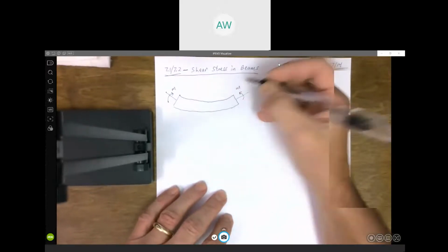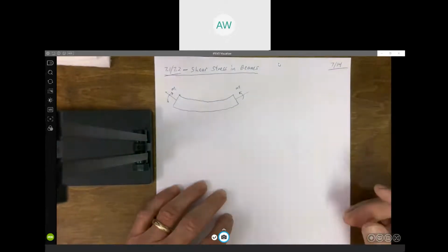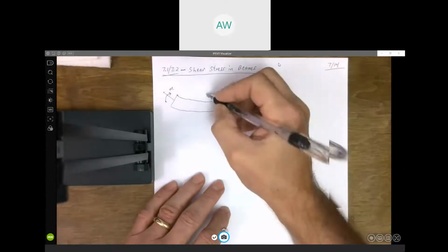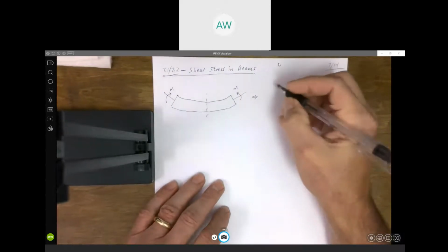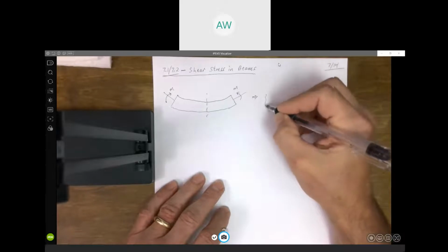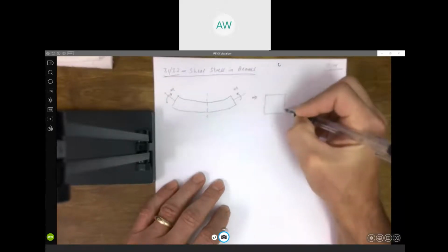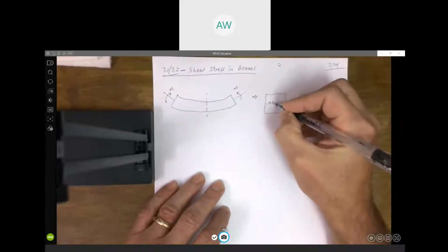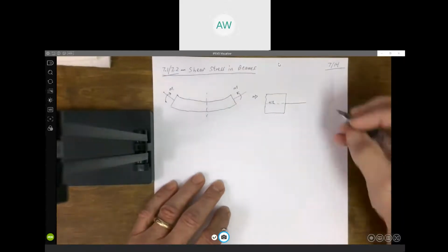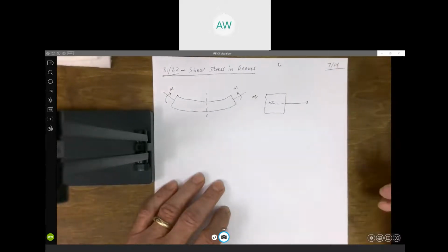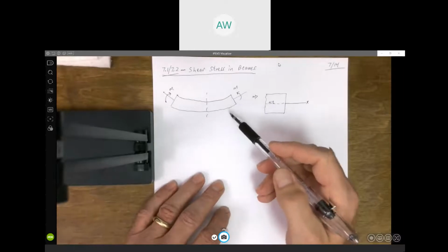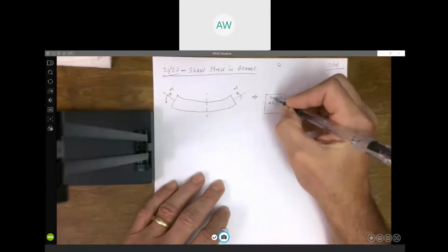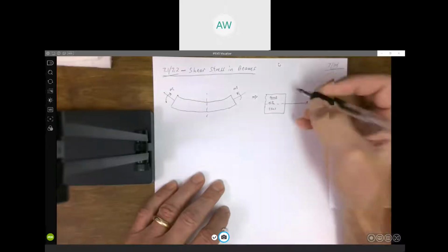It's going to cause this beam to deform, bend, and we saw previously if we cut this and look at the cross section where we cut it, there's a surface where the stress is zero that separates tension and compression. For a moment applied in this direction, it's causing the top to be in compression. So up here we'll have compression. Anywhere below that neutral surface we have tension.